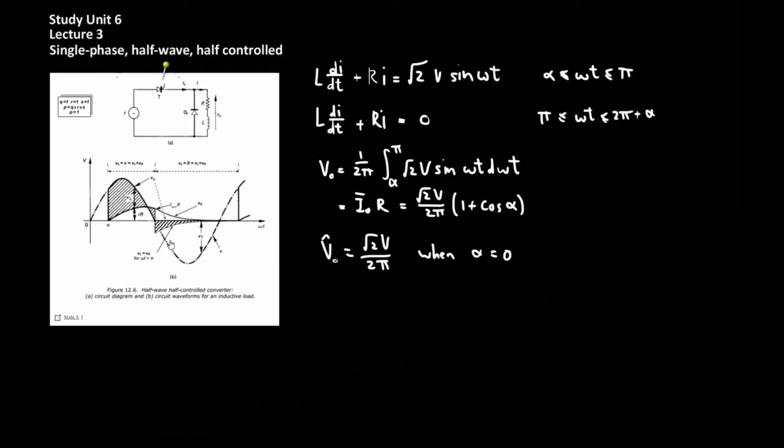In the rectifiers I have considered thus far, during the negative part of the input signal cycle, energy can be transferred from the load back into the supply. In half-wave rectifiers, this is rectified by making use of a freewheeling diode, which is in a shunt configuration with the load. So essentially what this diode does is that it tries to prevent the output from falling to a negative voltage, which would cause current to flow back towards the supply.